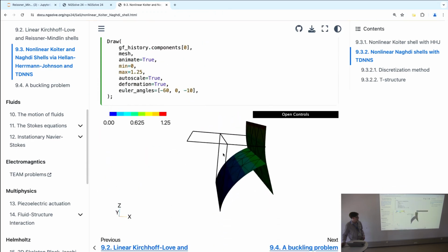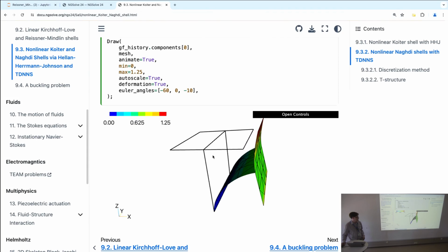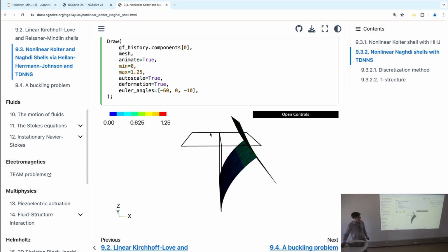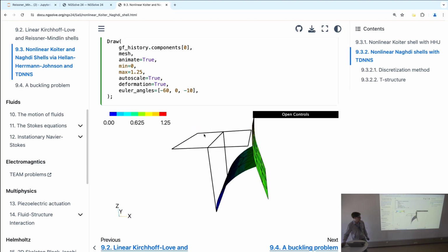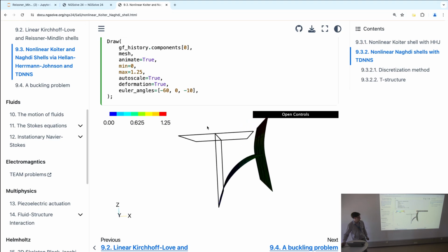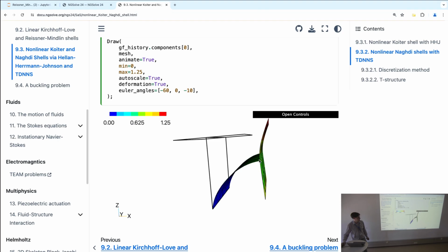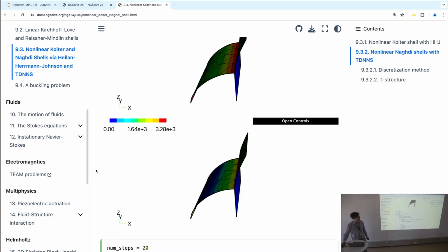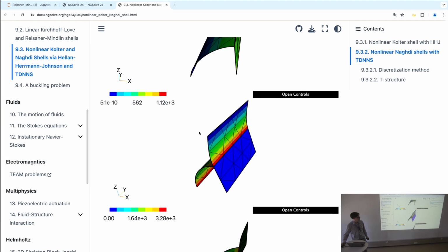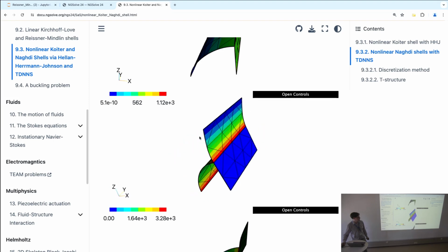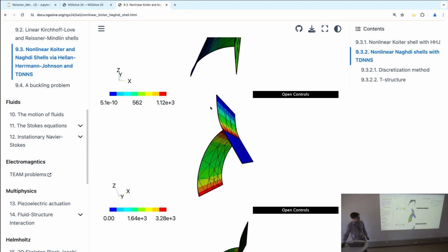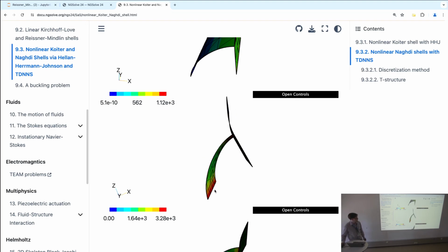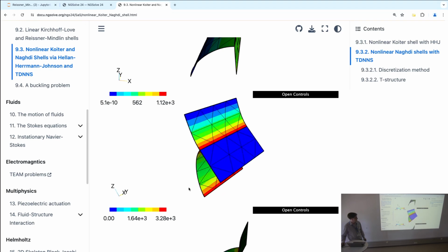So yeah, we see here we have a very huge shear force in this direction, and it rotates about 90 degrees. And we see that if we would zoom in, the angle is still about 90 degrees. Also, if I look at the bending stresses, we see that the whole bending stresses are only at the left branch. The right branch undergoes a pure rotation, which makes physical sense. So all the bending induced here goes, the stresses go to the clamp boundary.